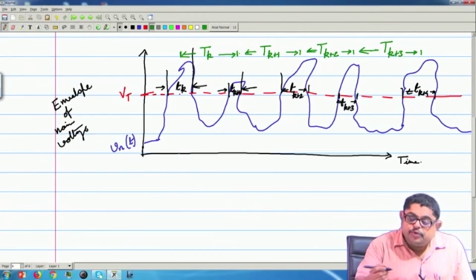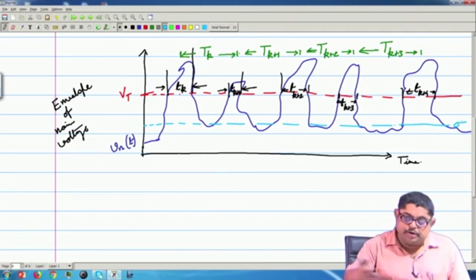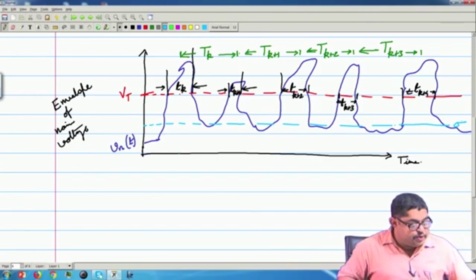And also I can have that based on the statistics of the noise, that is, what is the noise power. So, this thing let me call sigma, the standard deviation. So, square of that, this is a voltage graph, so square of that will be power.